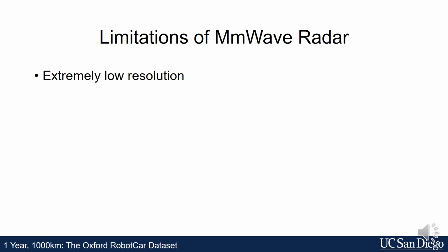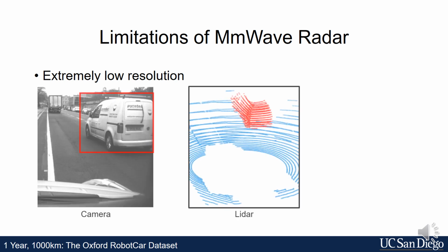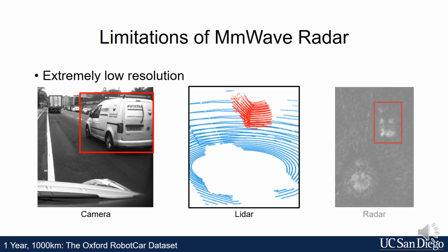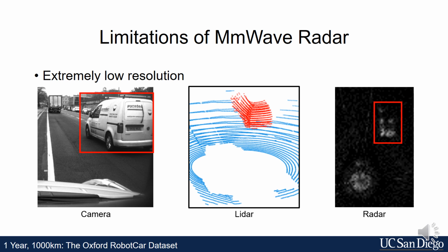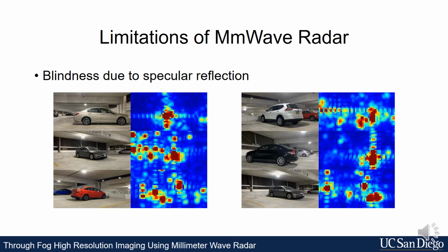However, vehicle radar has two main drawbacks. First, the radar has low spatial resolution due to its small form factor. While visual sensors reveal fine-grained shapes of targets, radar only generates intensity maps with strong reflection peaks. Second, vehicle radar typically emits millimeter-wave signals, which are specularly reflected by most objects and may not be captured by the radar. These figures show the aligned camera images and radar intensity maps of different vehicles. The radar can only see parts of the vehicles with strong reflections towards the radar.